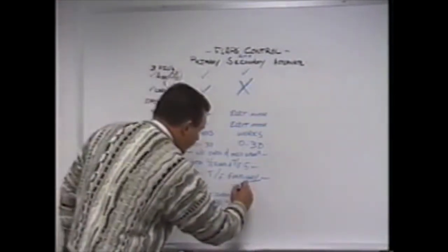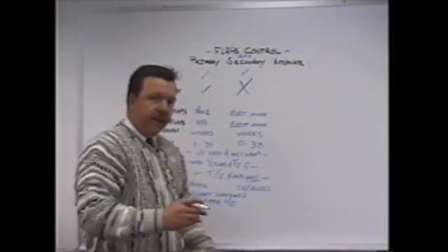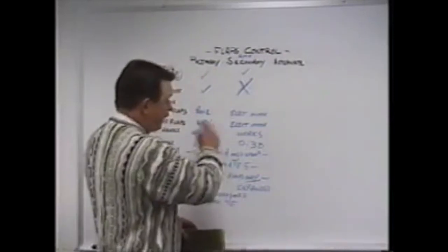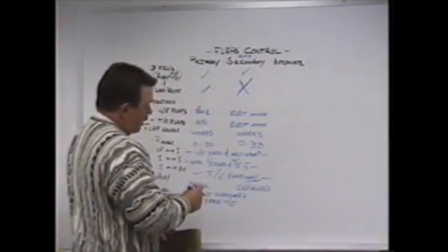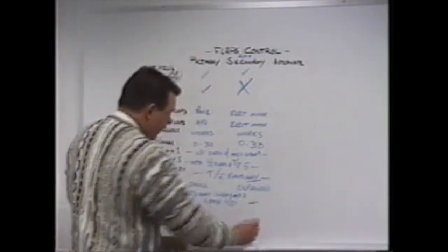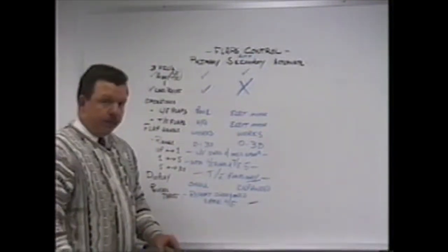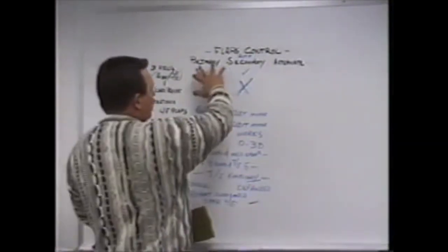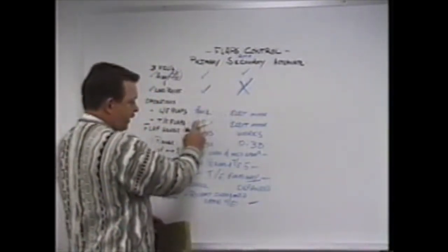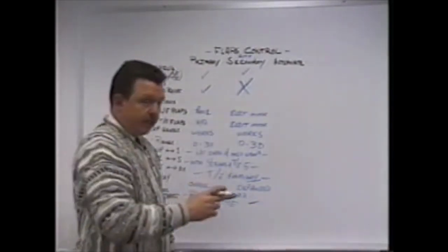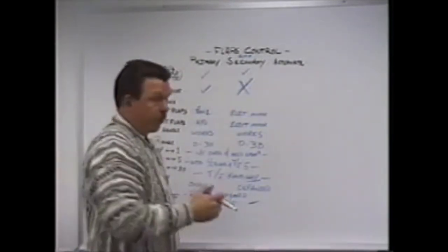Your display in the secondary mode is expanded. You have 4 vertical tapes for your trailing edge flap segments and 6 leading edge boxes for your leading edge segments. Again, going into reverse thrust will retract the inboard and midspan leading edge flaps in the secondary mode. Basically, the only difference between primary and secondary is the amount of time to operate the affected set of flaps, because electric motors are a lot slower, the display, and no load relief. It's the only difference between primary and secondary.